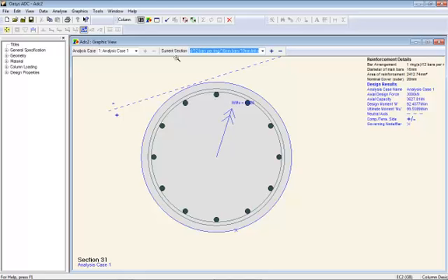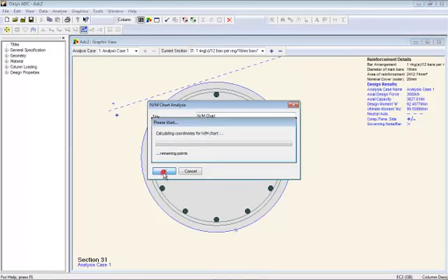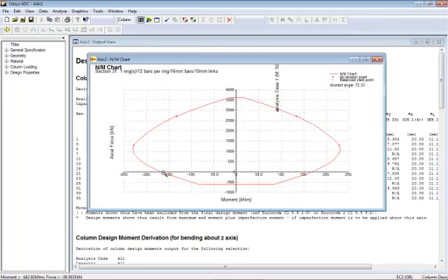Or we can choose a different section, but we can also then look at how hard it's working. Let's look at the axial moment chart, and you see there's the axial moment chart curve. As long as we're within this boundary, we're okay, and it's automatically marked on that load combination onto the column to see where it falls. But you can see how much moment is also added on.